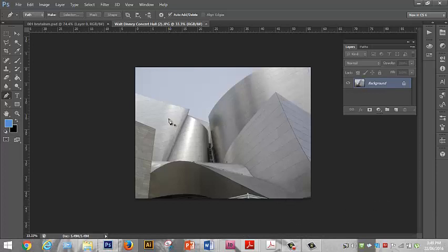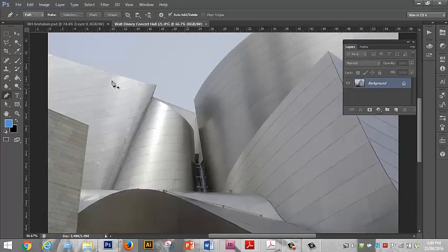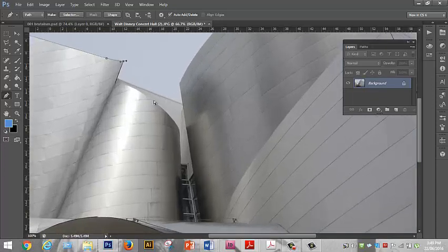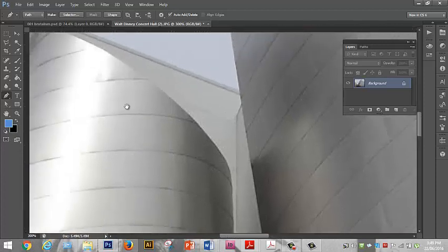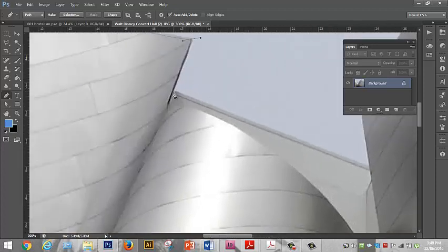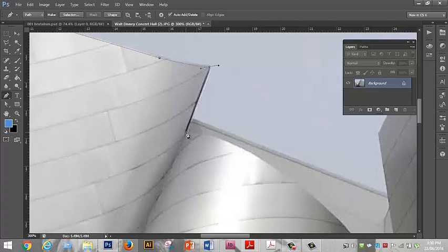Right, so curves. Curves are a different proposition. Rather than clicking, moving the mouse, then clicking again, this time we need to click and, according to how severe or great the curve is, move these little moustaches. You click and drag, and I'll do that. I need to zoom in. Control plus, space bar, and there we go.